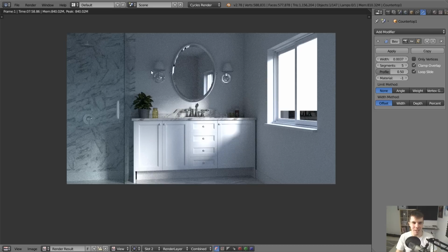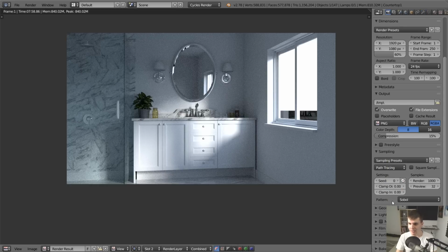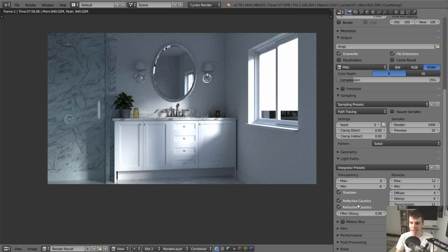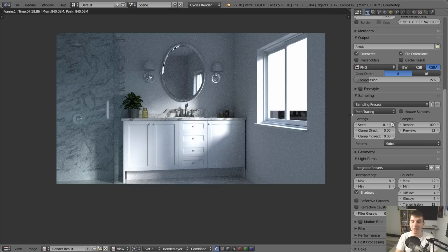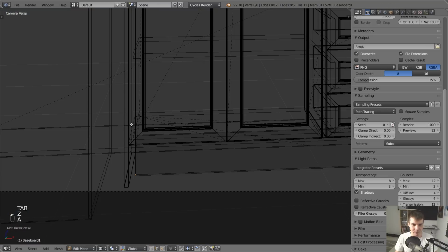One thing you might notice is that there are fireflies around. They're not that obvious, but that is because underneath our light piles down here, Cycles is rendering caustics for everything. And I personally just don't see a use for them, so I'm disabling them. I've tried to stay with caustics, but in almost every situation they just make the render worse because there are fireflies everywhere. I really want caustics, but I just haven't been able to get a nice result with Cycles.